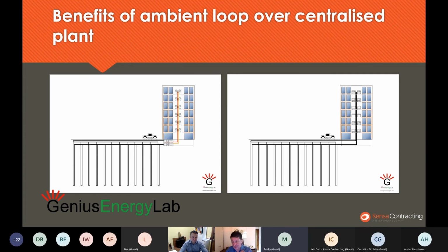Whereas when we're looking at distributed heat pumps, we can run at low temperatures to do the space heating, and then only boost up to domestic hot water temperatures when we have to. And in a new build, that might be 60% of the time you're doing a much lower temperature space heating, and only 40% of the time you're up at domestic hot water temperatures. In retrofit, actually domestic hot water might only be 10 or 15% of the runtime. So it's a much better solution.